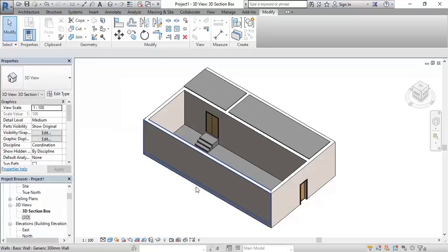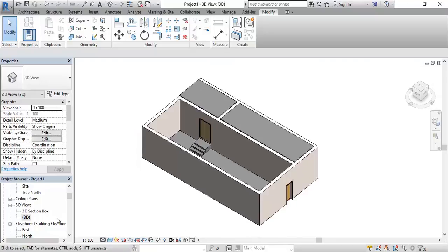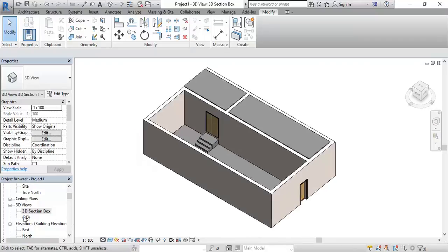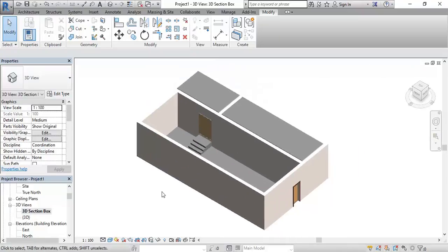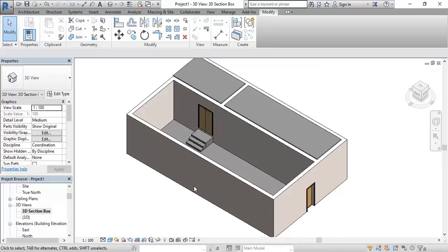Okay, so there I've got a new view, but at the moment it's identical to the previous one. Right, so double clicking on those, you shouldn't see any difference except that one might be zoomed a bit differently, but otherwise they're identical, unless you change it. So, don't know if you remember the section box tool in your view properties. You can find it usually just by scrolling down a little bit, and you'll see there's a group of a lot of tick boxes, and you should be able to find the section box option, which you can just tick.